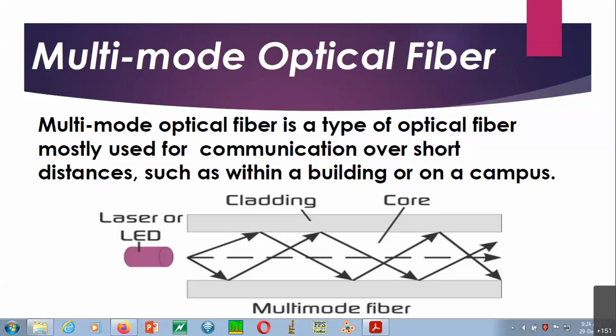Before, I was happy with this 1 gigahertz signal, but then I realized that 1 gigahertz may not be enough for my purpose. Then I need to increase the frequency range. If I go beyond 1 gigahertz, then this coaxial cable will not work properly, because it has a limit of only 1 gigahertz. So they came out with another idea: the waveguide.